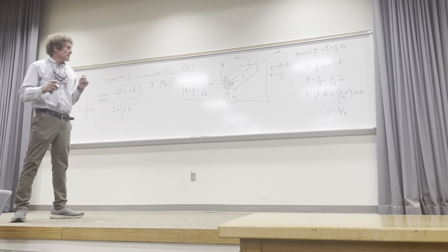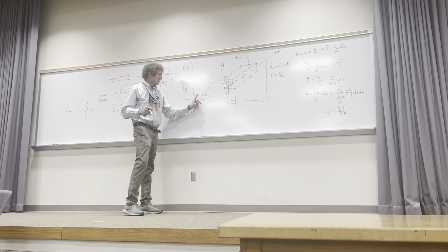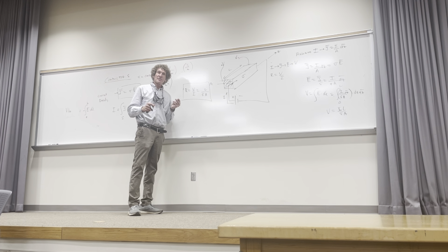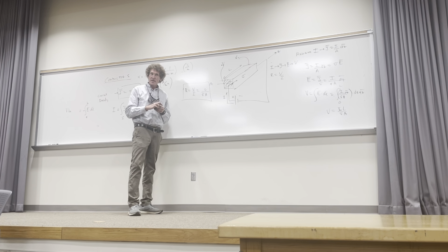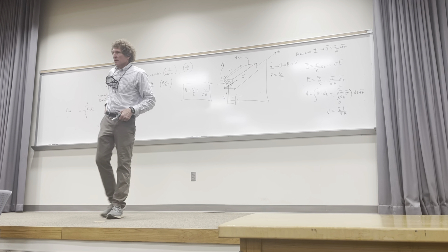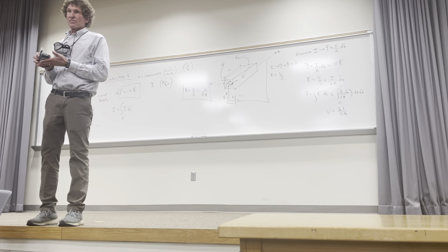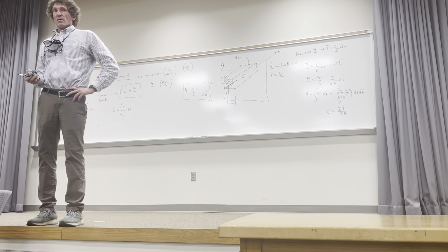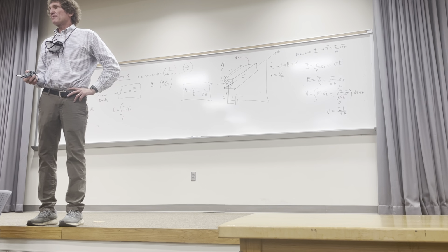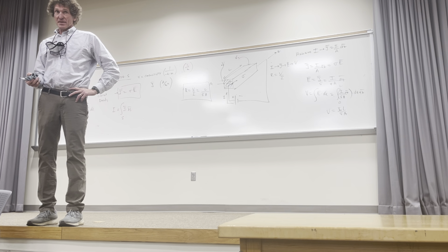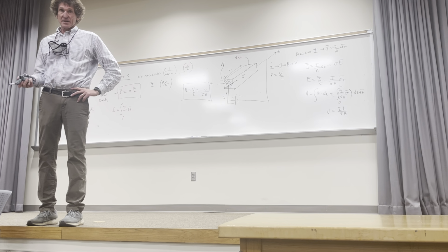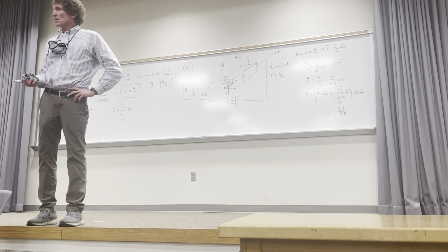And you'll realize it's inversely proportional to the conductivity. So the higher the value of conductivity, the less resistance you would have for a given geometry. Does anybody know what the conductivity is of copper? Pure copper. All right, it's about 5.8 times 10 to the 7th, 1 over ohm meters, if you look in the back of the book. That's very high. Silver's a little better than that.